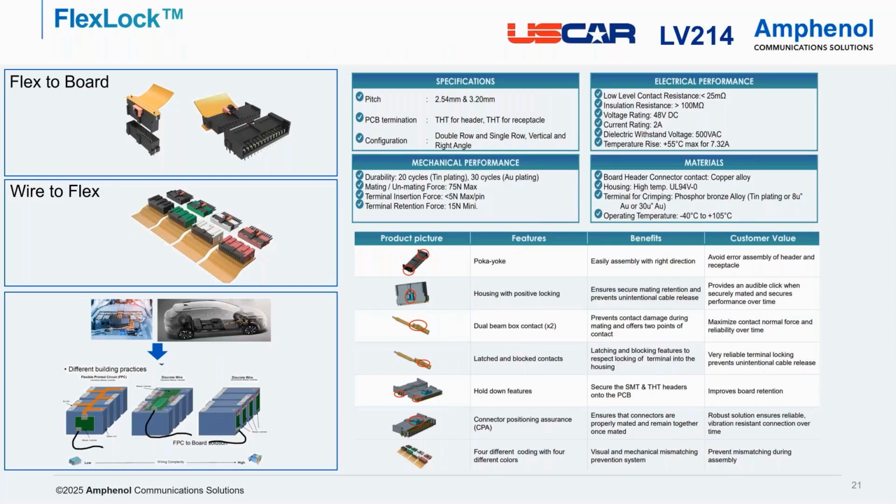The connector fulfills also all automotive requirements, and because of the larger pitch, we also fulfill the 48-volt requirement with this connector, which is today a new requirement within the automotive. The current rating is at 2 amps, and if you have a 55 degrees Celsius temperature rise, you can go up to 7.32 amps.